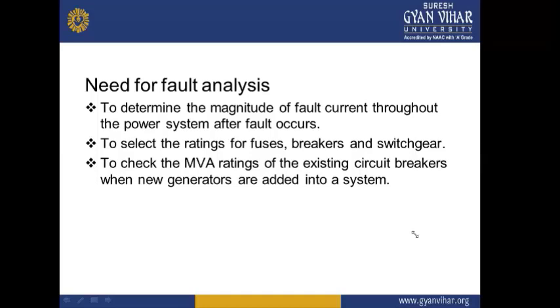So basically, we require short circuit analysis or fault analysis to identify the MVA ratings or the short circuit ratings of the various equipment which are going to be connected into the power system networks in reality.